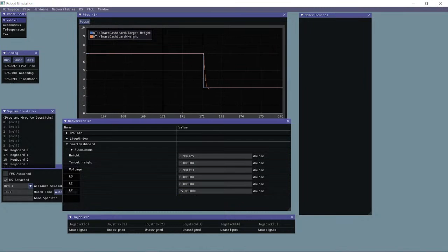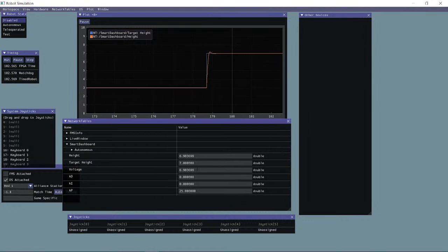I'm going to cheat and do what I tuned before. Okay, so I'm going to work with this. It has a small oscillation, so it's coming in pretty fast, and we can just use KD. What if I do a little bit more? We can use KD to slow it back down. So I do 100, and then I change the set point.